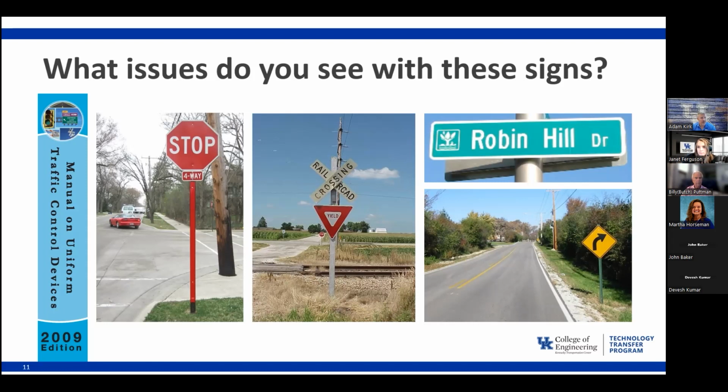Here we've got 2 signs on 1 post with the railroad crossing, and this one actually is permitted in the MUTCD: you can dual mount a stop sign or a yield sign on the railroad crossbucks. But if you look at the railroad crossing, we've got a lot of fading, and the general overall maintenance with that one is poor. But this is the one location where you actually can dual mount 2 messages on a single signpost.